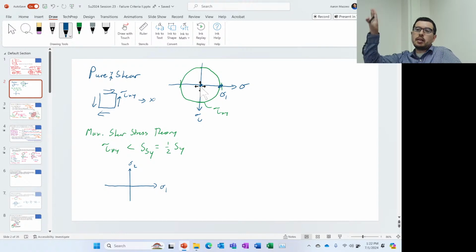I could say, okay, there's 3D, right? But if I'm just looking in plane, I've essentially got only two options. I've got a pair, and they are all on the circle, whether they're tau xy and a sigma, or my sigma x, my sigma y, and my tau xy. Those three values have to be on the circle. None of them are on the origin.